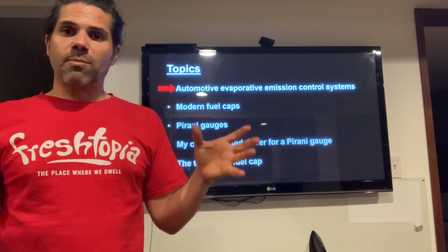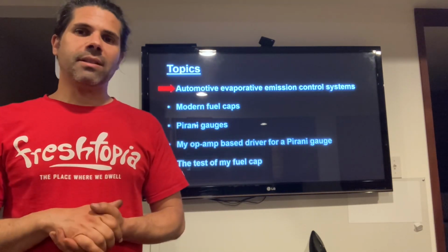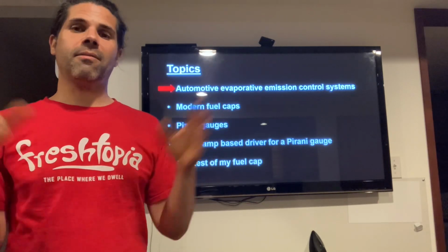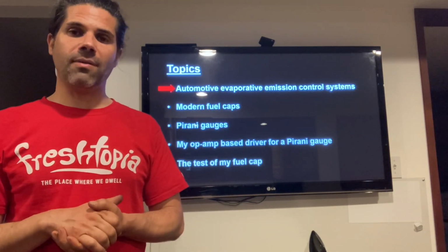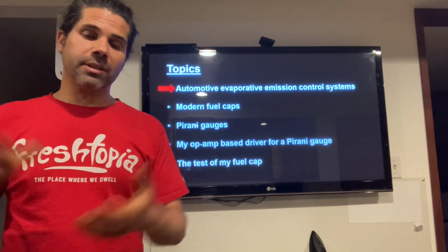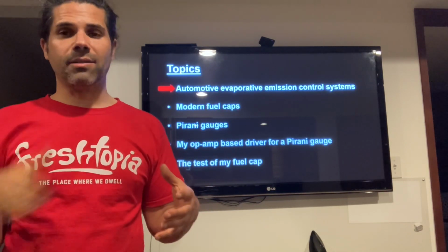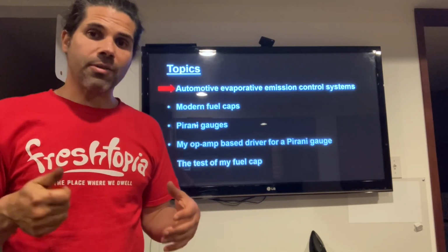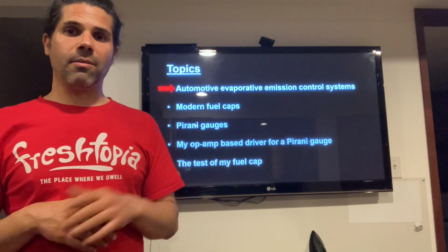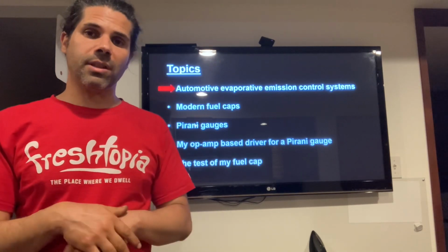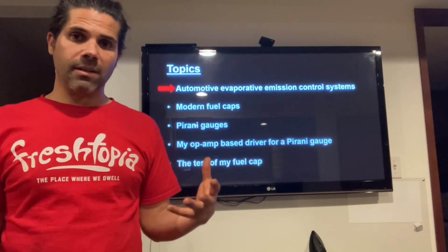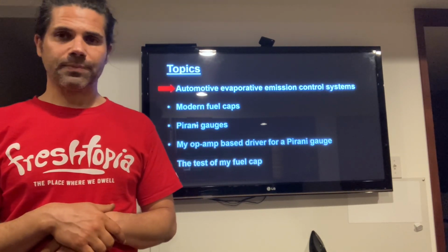Gasoline vapors cause smog. They're air pollution, basically. So when your car is off, the last thing anyone wants is your car putting gasoline fumes out into the environment. So when you shut your car off, a vent valve closes and seals your fuel system so those gasoline vapors can't get out. When your car is running, you do not want the gasoline system sealed because you need makeup air to make up the gasoline that goes into the engine. So you need it vented. You need it open to the atmosphere.